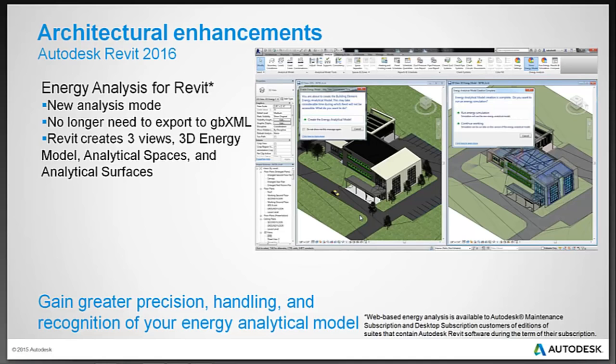The name of the mode, excuse me, is use conceptual masses and building elements, and the both types of design are conceptual mode and building elements. This mode can be helpful if you have a design that is partially detailed and partially conceptual, or when you have modeled conceptual masses to represent additions to an existing building that is fully modeled.